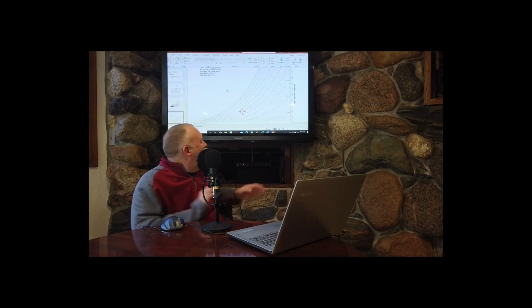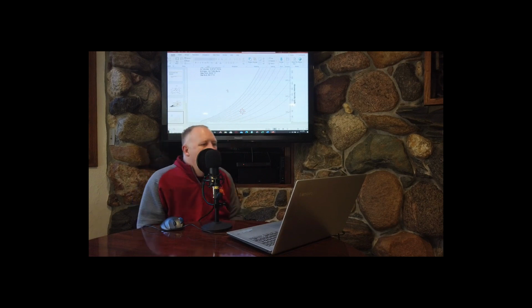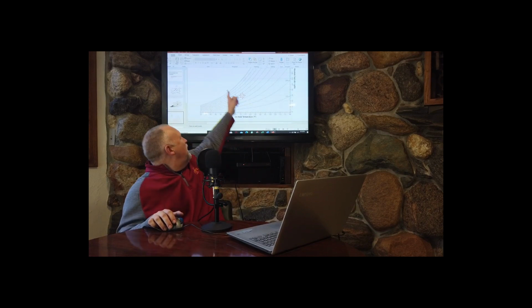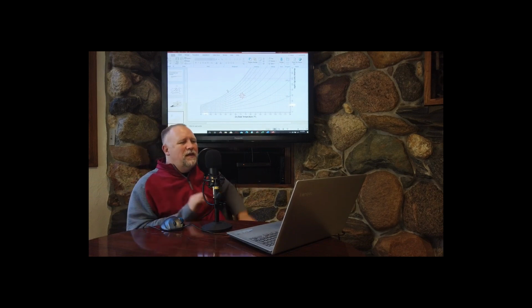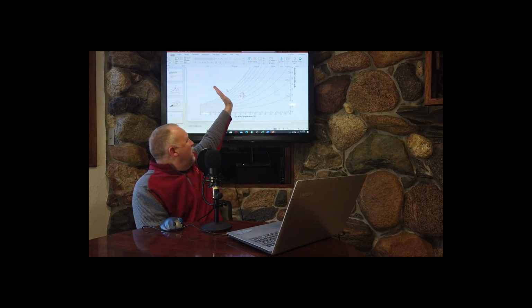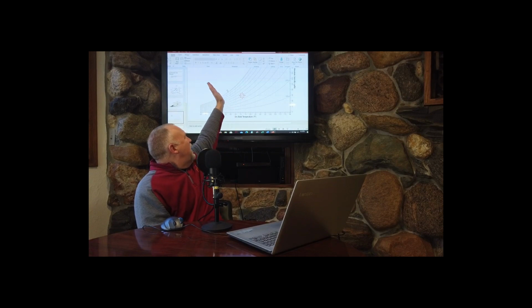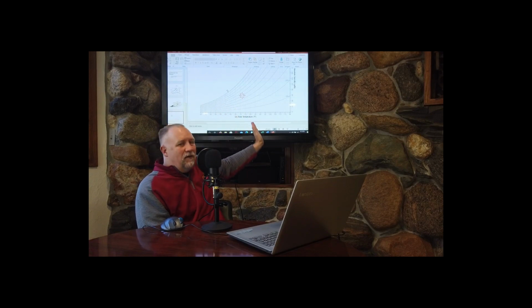And then enthalpy, if you go past the saturation line to those axes that are out here, enthalpy should be around 18.8. Here's a tip to get the enthalpy correct. On your psych chart, there's an enthalpy line out here and then also along the bottom. If you put a long ruler across there, and you've lined that ruler up correctly, it'll be on the same enthalpy line up here and down here.